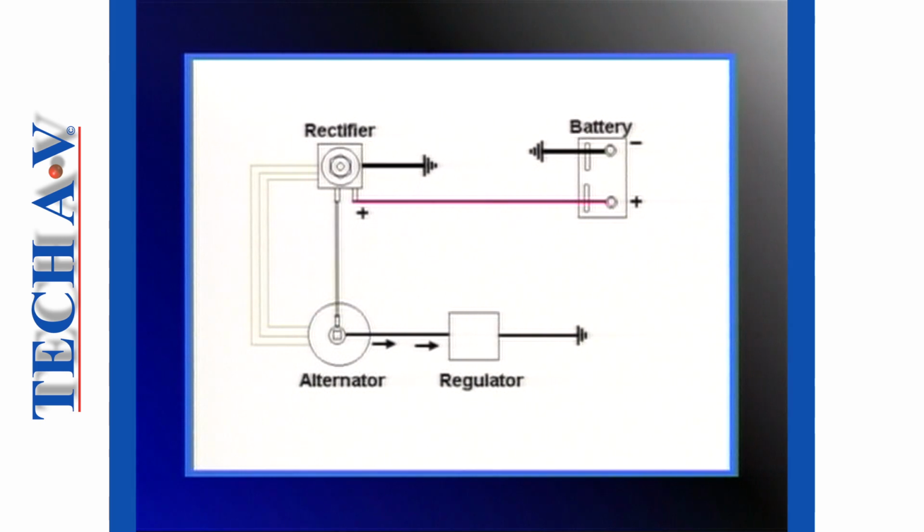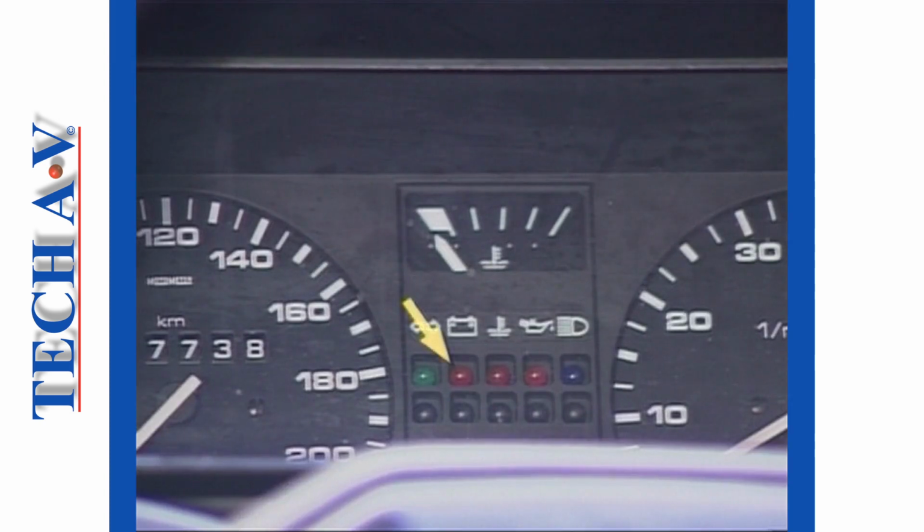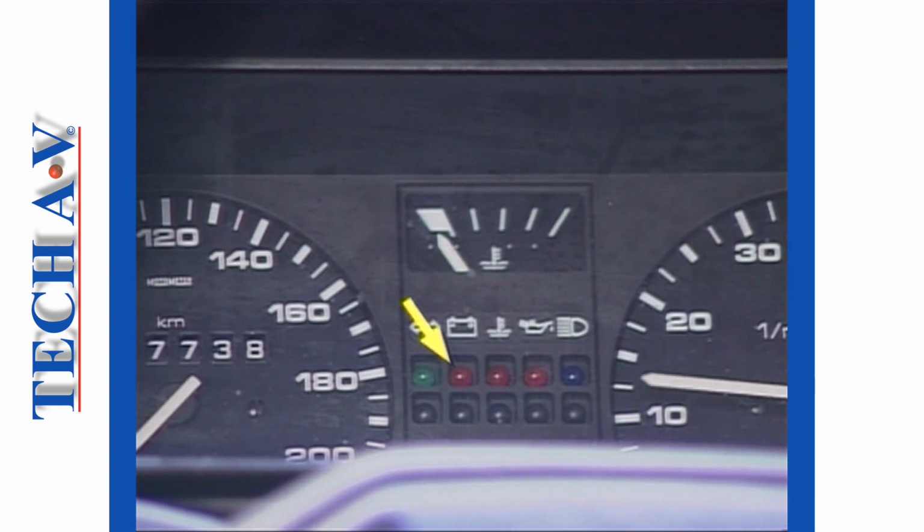The voltage regulator senses the battery voltage and the alternator output. It then electronically changes the strength of the field depending upon the load requirement. A warning lamp on the dashboard or instrument panel lights up when the system is not operating, it goes off when it is operating, and it comes on to warn the operator if the system is faulty during operation.